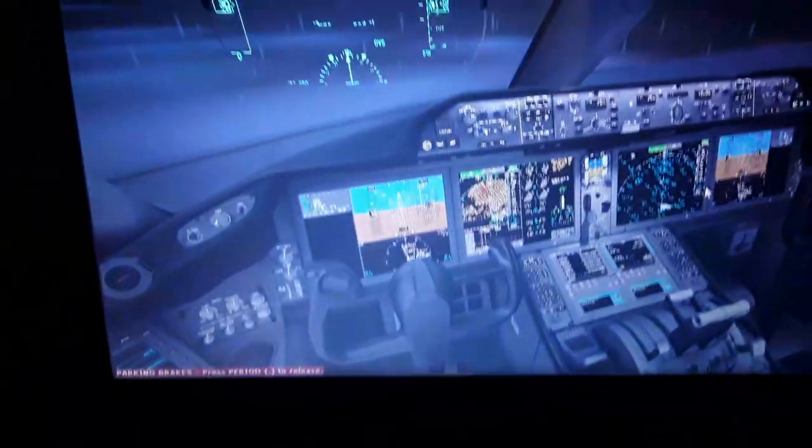the pressurized air from the left and the right engine, from the 5th and 9th stage for cabin pressurization, engine anti-ice, air conditioning, ventilation, hydraulic fluid tanks pressurization. Also the FADEC controls the fuel recirculation from the wing tanks, from the left and the right wing tank and the center tank to the engines for heating up the fuel in flight so it won't freeze. Also the lubricant and the oil. So we have the oil and fuel recirculation system automatically from the FADEC.